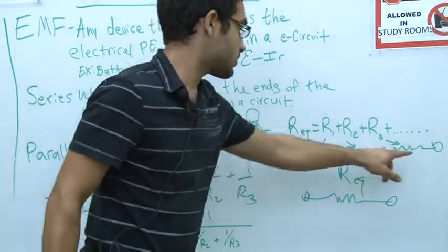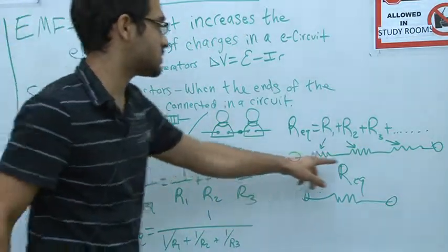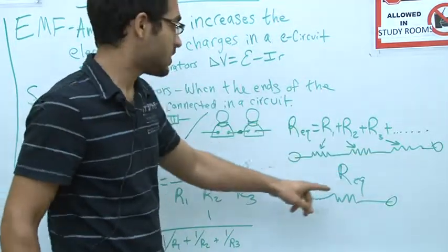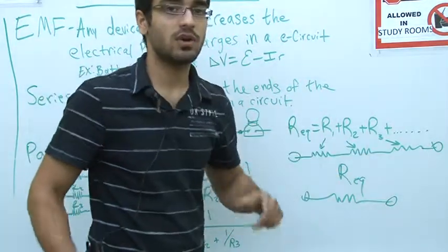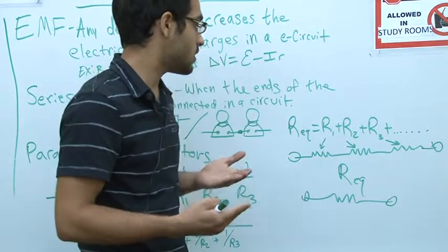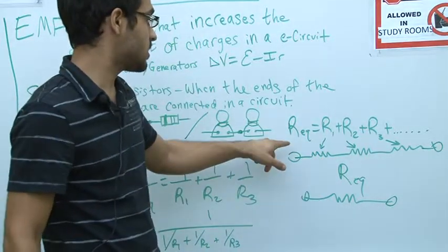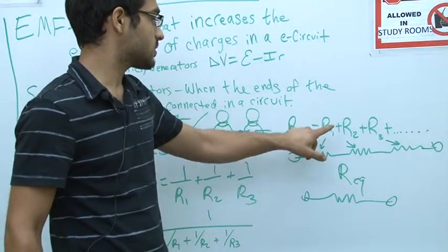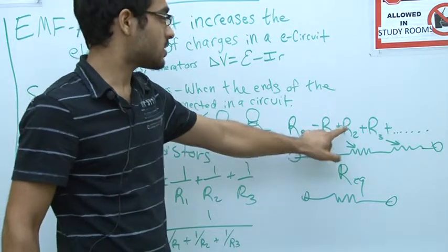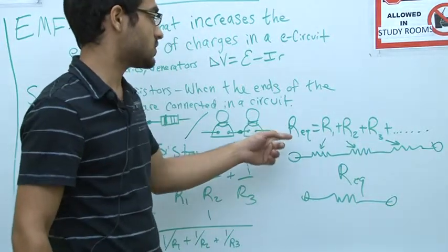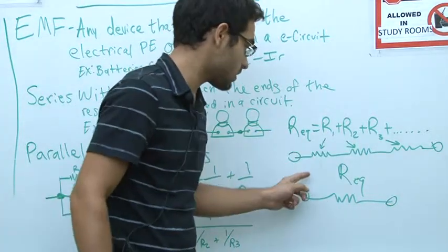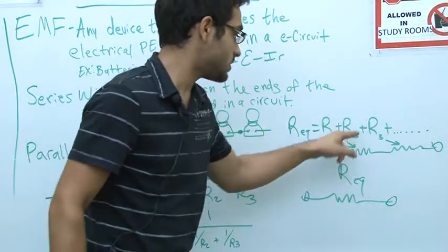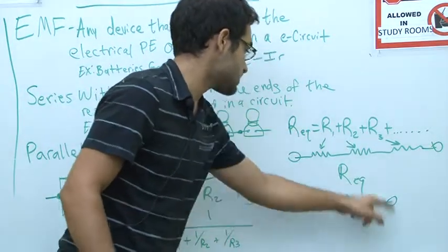If you wanted to know, let's say you had 3 resistors, or possibly more. You wanted to add up the resistance. Let's say I had a different value for each one, and you wanted to know the total equivalent resistance. Well, that's simply R equivalent equals R1 plus R2 plus R3, as in resistor 1 plus resistor 2 plus resistor 3. And you can see that all 3 of these is the same thing as this.